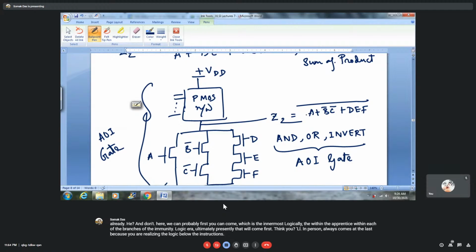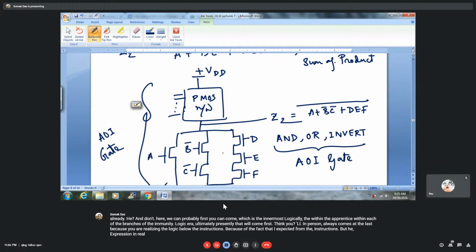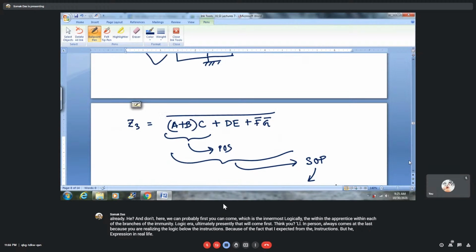This is because the most basic kind of CMOS logic is extracted from the concept of a CMOS inverter. So inversion is the inherent logic demonstration of a CMOS circuit. Any expression you realize within your NMOS network gets inverted and then the output is found.